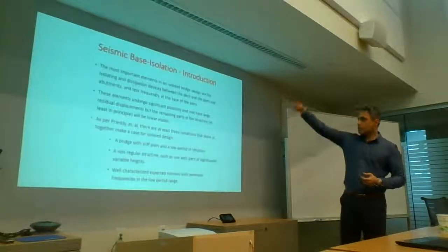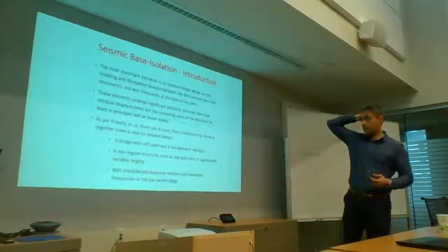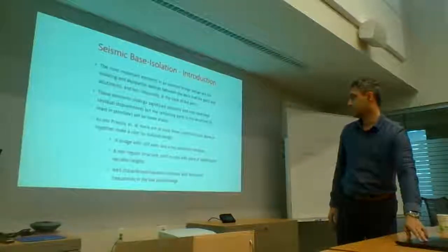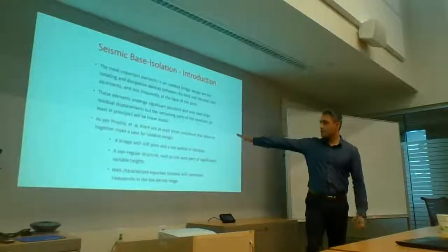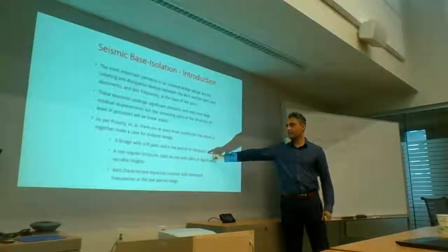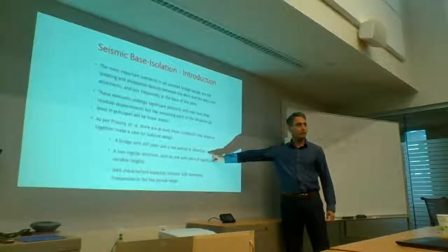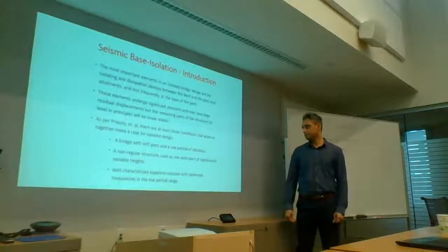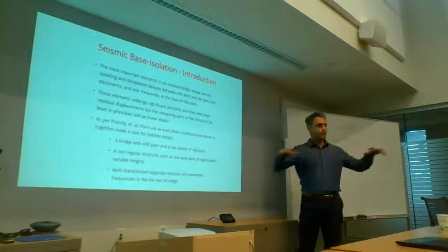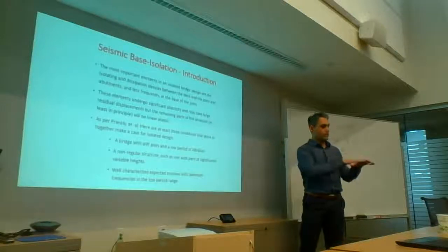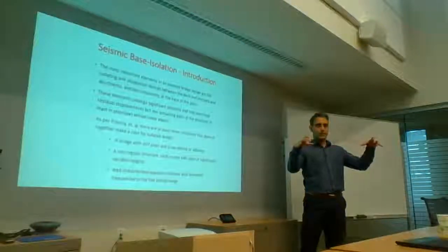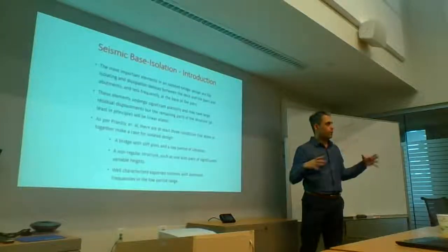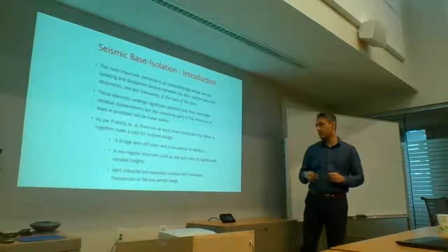Okay, so these elements may undergo significant plasticity. You've got to make sure that you control your displacement. That's a big thing. So the 3 big conditions: you should have big or stiff piers and a low period of vibration so that you move it, you lengthen it. If you have a lot of irregularity in your system and one is going to get hit more, then you can bring in these devices and you can tune them properly so that you get uniformity of response happening.